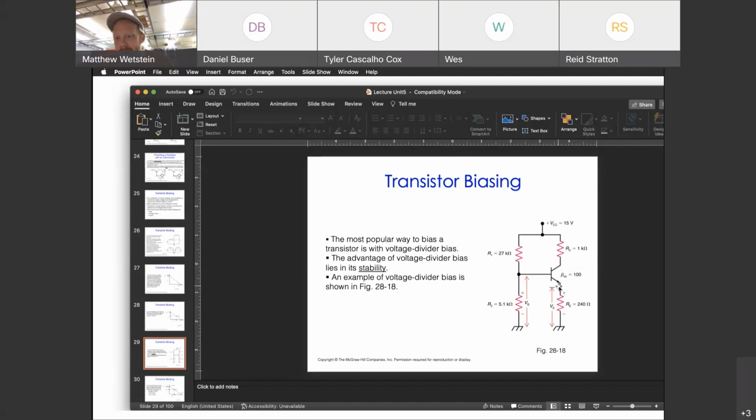So zero current to the base is one endpoint of your load line. It's the point where you have minimum current but maximum voltage. After that, any current you apply to the base is going to increase the current going through VCE. Now, this is another one of the relationships that has to be true: IC or IE, I should say, those are two separate currents, have to be equal to beta times the base current, IB. And in fact, technically IE, the emitter current equals beta times IB.